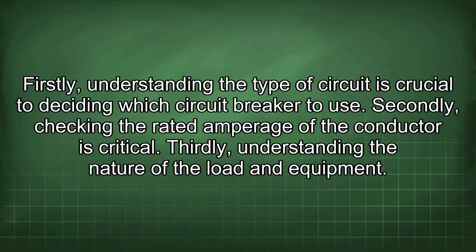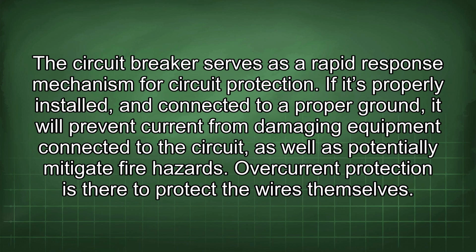Secondly, checking the rated amperage of the conductor is critical. Thirdly, understanding the nature of the load and equipment. The circuit breaker serves as a rapid response mechanism for circuit protection. If it's properly installed and connected to proper ground, it will prevent current from damaging equipment connected to the circuit, as well as potentially mitigate fire hazards.